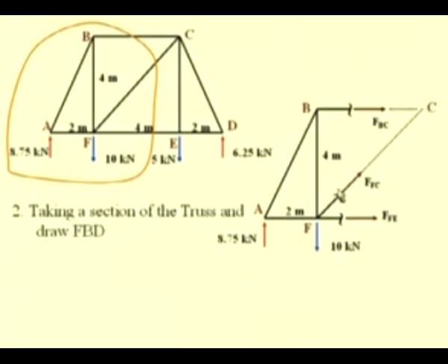Same way we see that the forces in the member FC and the member FE are concurrent at F. So, it is judicious to use a moment summation about this point F to determine the force FBC. And the third equation could be a force summation equation to determine the force in FC.